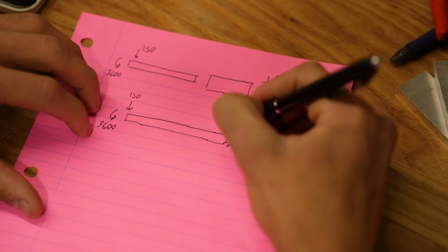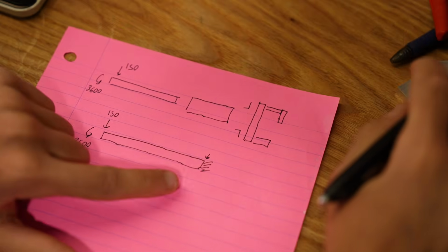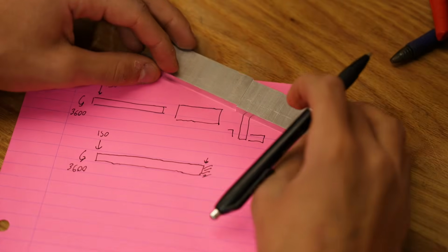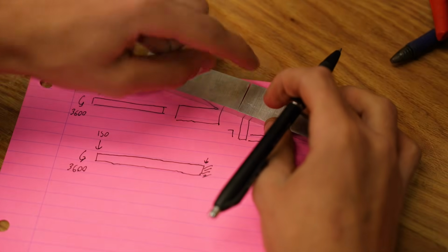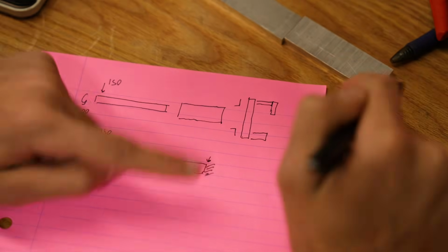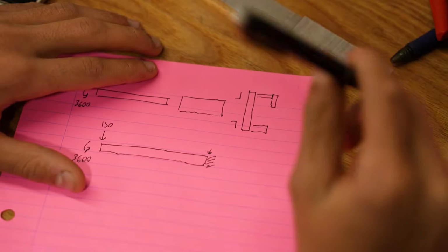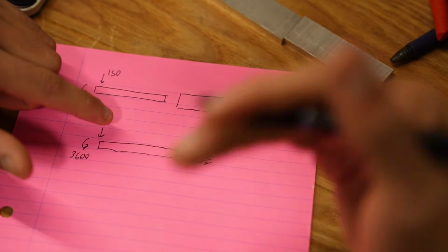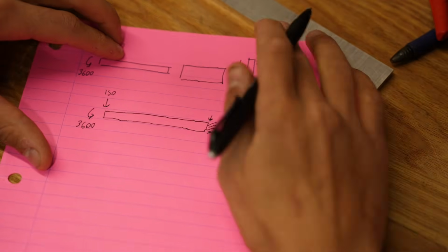The point of interest that we're going to analyze is going to be on the very top of the section here. So as the pole is bent, it's going to want to crack right there on the top. Torsion is equal across the whole thing. The whole thing resists twisting equally. So we're going to just calculate for the outer surface, particularly on that top edge.